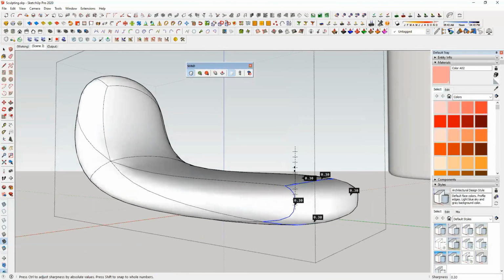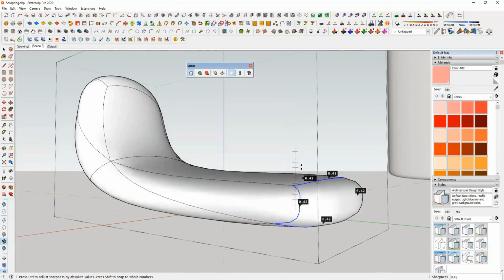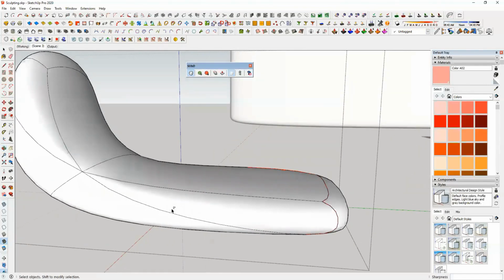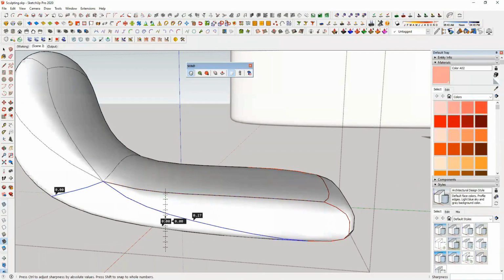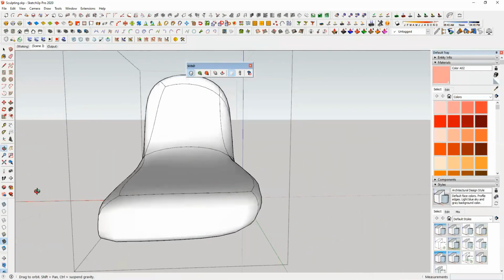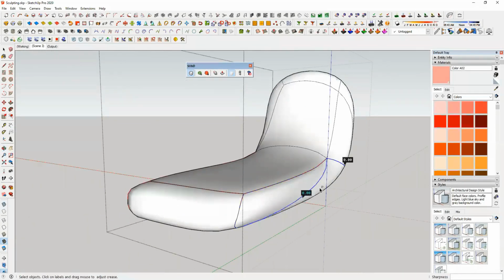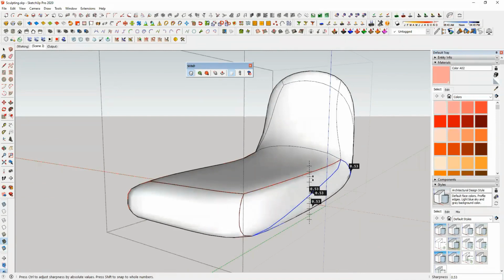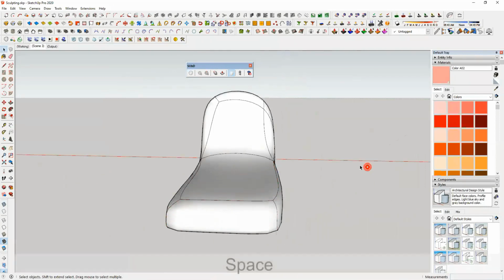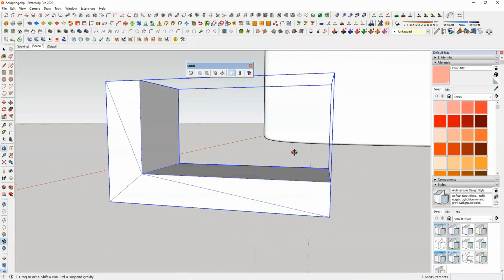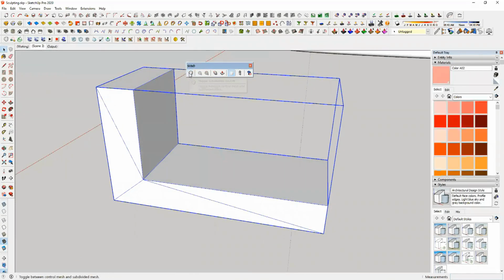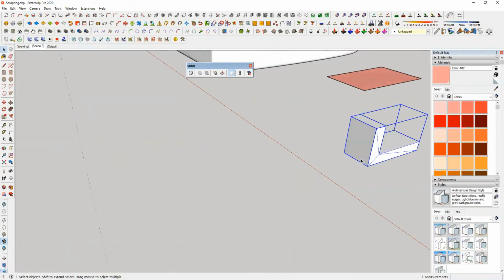So I'm going to select here and modify this to this level. So we are sculpting it, but we are also modifying the shape. As you can see, we have this flexibility as well. And click outside. At any point of time, if you want to change the original model, then you can go ahead and turn off the subdivision and start adding more details to it.